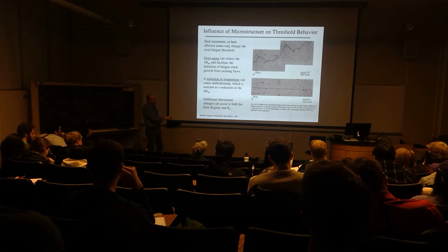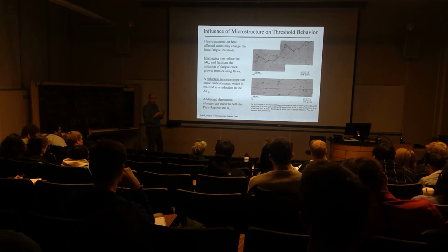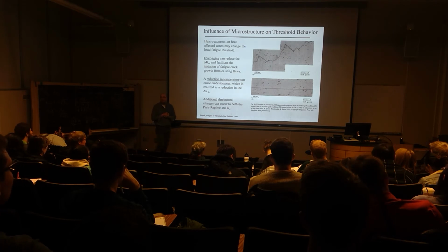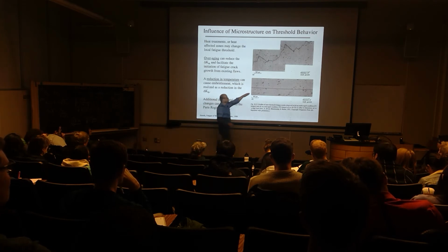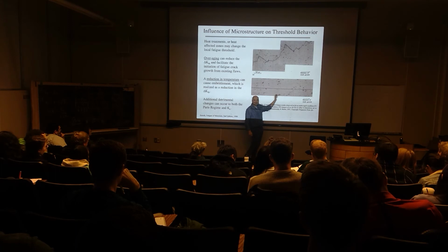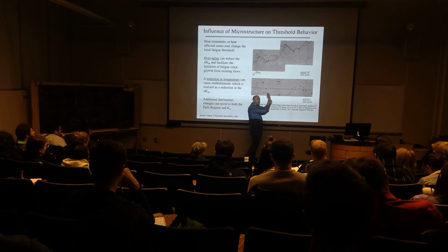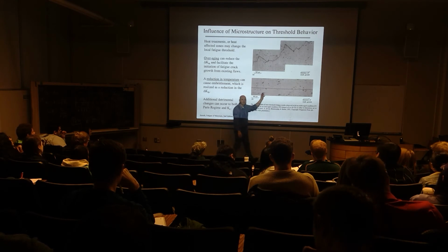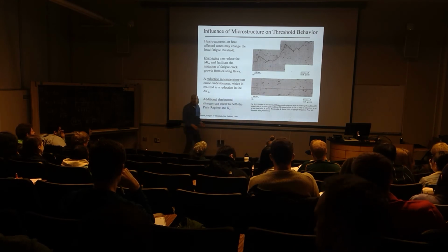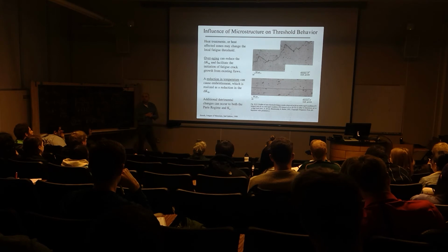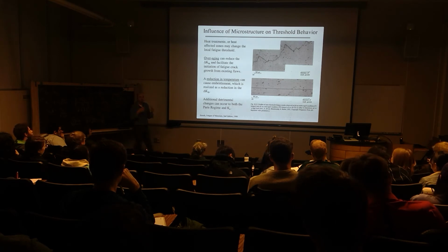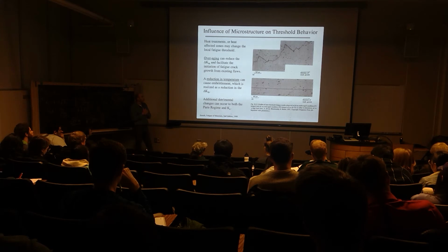And then in this case, this material has no microstructural obstacles that are actually preventing that crack from growing straight. It just simply grows according to the direction of the maximal opening mode stress. Simply a result of overaging and minimizing those precipitation hardened zones to be the appropriate size according to knowledge of the plastic process zones that we want to achieve.